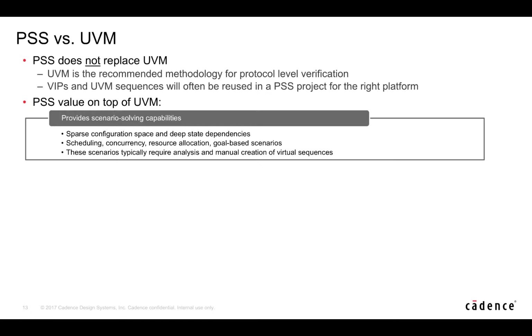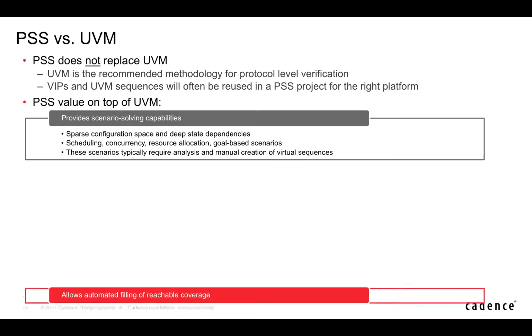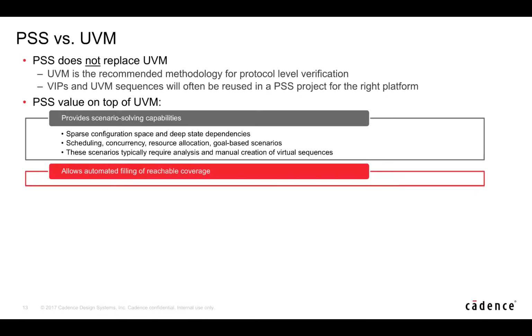my test. The other thing that PSS does very, very efficiently, if you're coming from a UVM background, you would probably see that PSS is generating the virtual sequence as opposed to a human engineer coming up with it. And of course it's coordinating things on the hardware side, traffic side, and software as well, right? So what's going on on the CPUs.